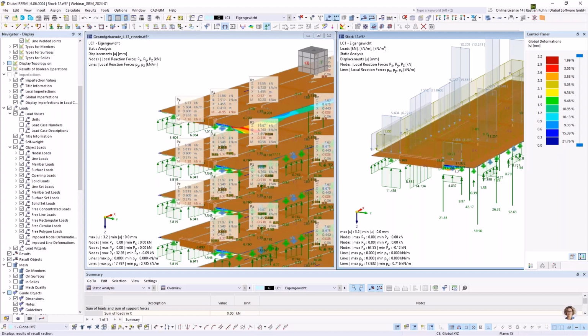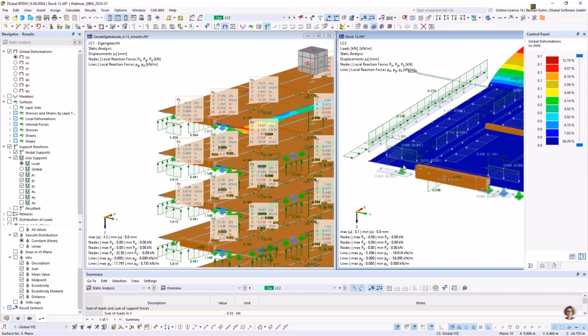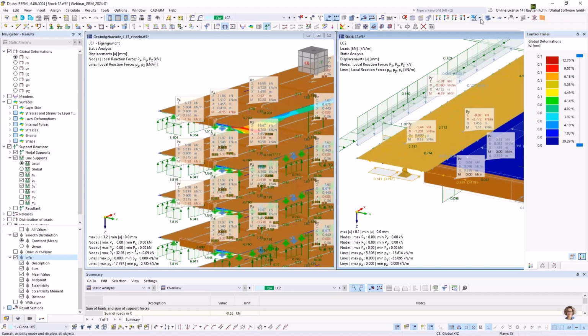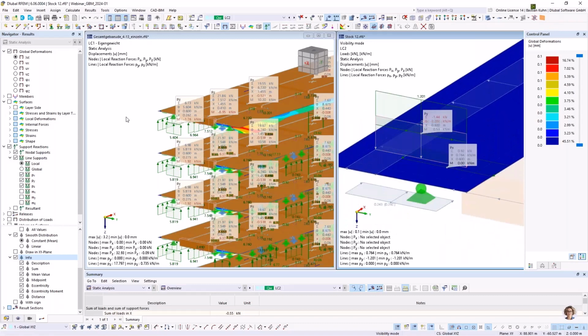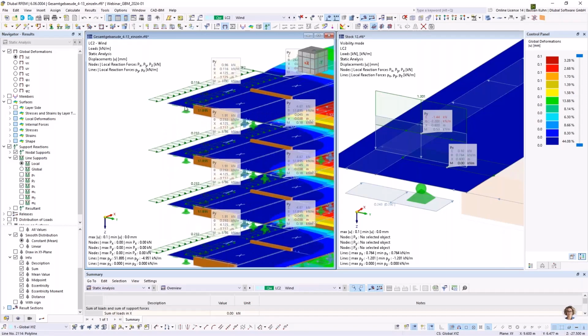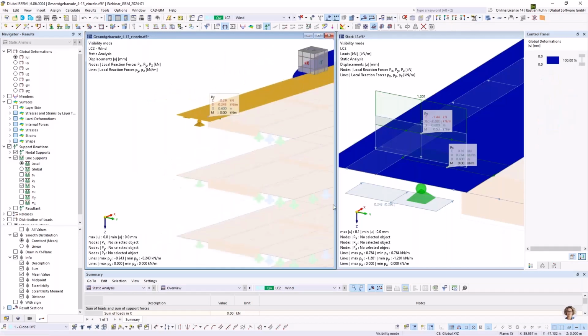Okay, and it can work the same way with the wind load. So when we take the wind, as we did here for the wind load case, and maybe again we look for the staircase for the concrete kernel, we have here a horizontal force, and here we also can activate the info box maybe, and maybe only visualize this in here. This is now this and this. And when we look for load case 2 in the bigger 2D model, this is this, hold on, do the same in here. You see that, yeah, 0.29 is the sum that we are having here as well.